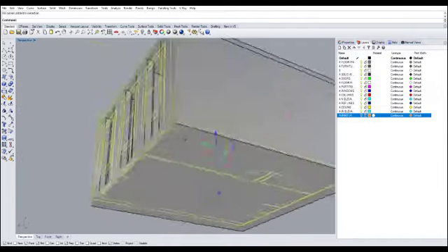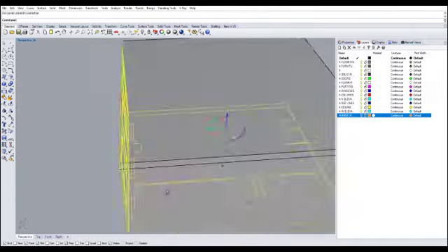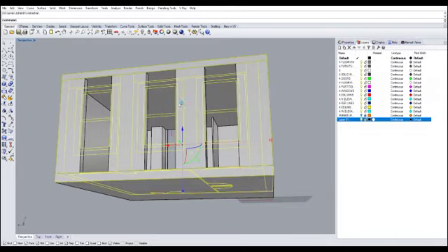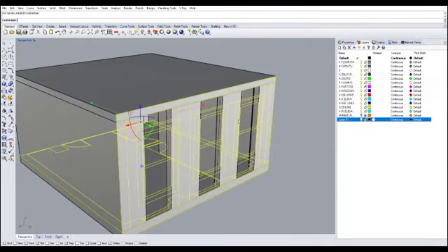It allows you to select all the curves, or simply lines or polylines, in your Rhino file. Once selected, they're indicated in yellow. We're going to put these into a new layer. Again, click new layer, and the new layer is created. Our lines are still selected. So let's bring all the lines into our new layer. Lines selected, new layer selected.